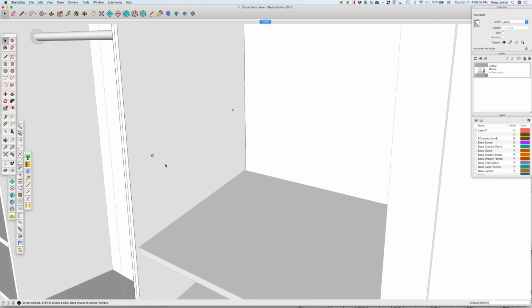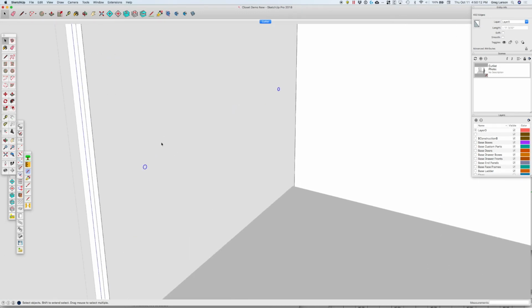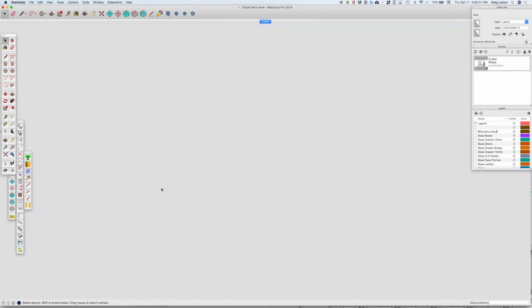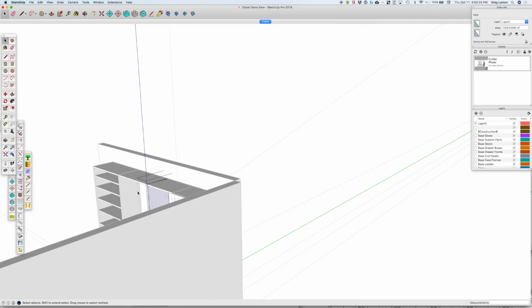So now all I got to do again, they're all selected. So I can just hover over one and right click, and again my multiple circle push comes up because they're already selected. I can do that, say 0.5, and I'm there. I've got those same holes punched in the same spot on the other side.